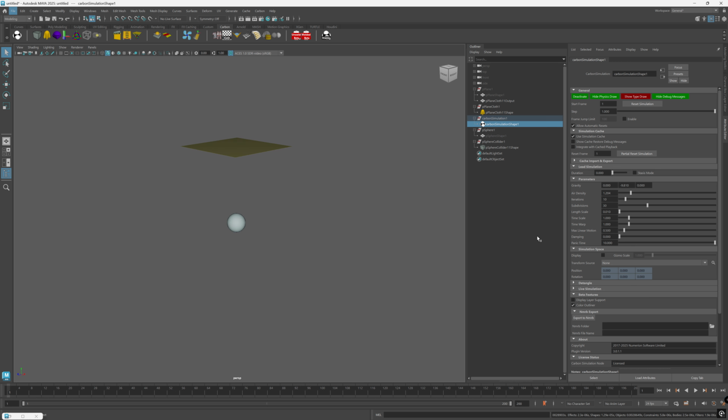Next up, maximum linear motion. Maximum linear motion is set per time step. It is a speed limiter and the maximum displacement per subdivision that the Carbon simulation will allow on anything. It is a useful feature to avoid objects disappearing into the horizon when something blows up, or keep high speeds under tight control. In practice, what does this mean?